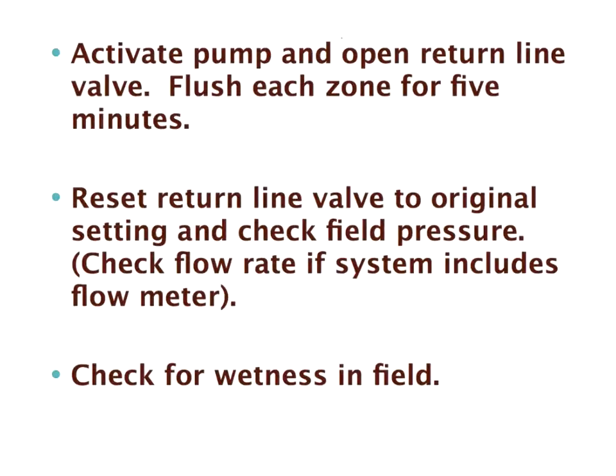Activate the pump and open the return line and flush each zone for at least 5 minutes. And we've got 5 minutes. You really want to flush anything out that might have got into the system. So if you flush for 5 minutes, you'll really clean the zone, and do it zone by zone, obviously.